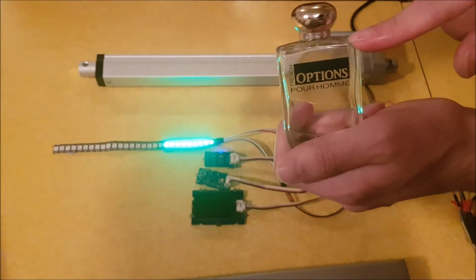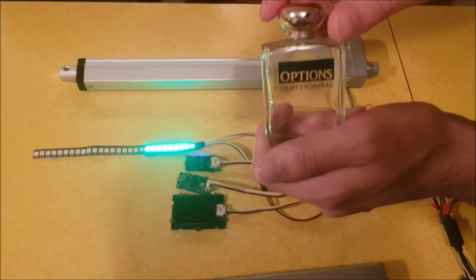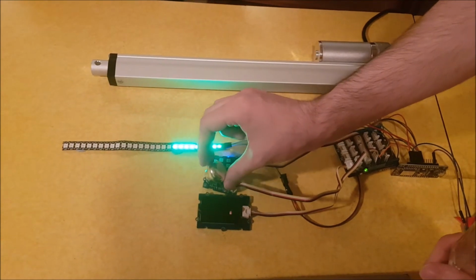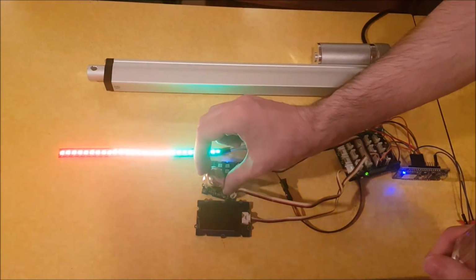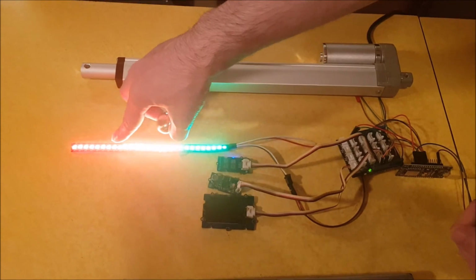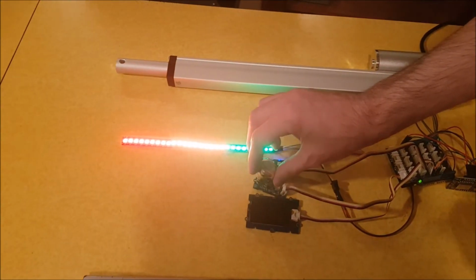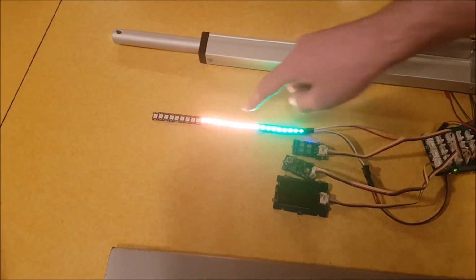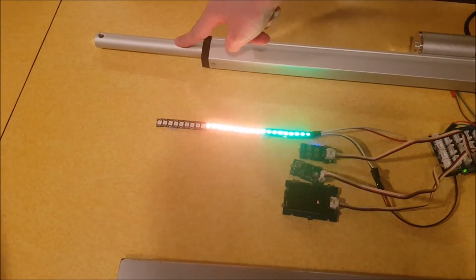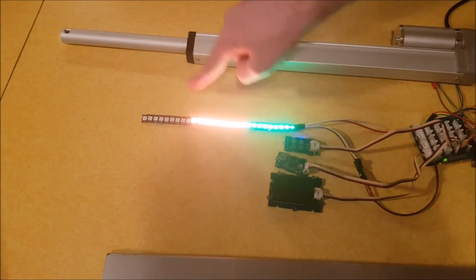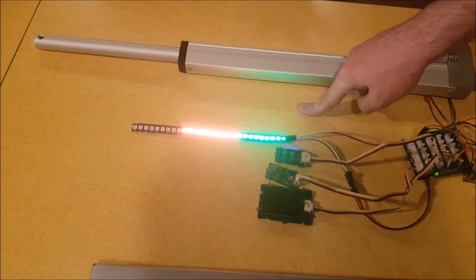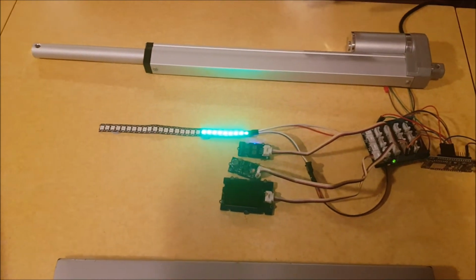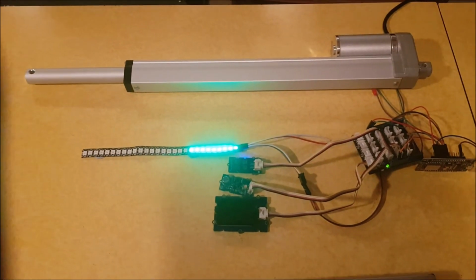Here we have some perfume which contains high concentrations of alcohol. When the bottle is shaken and some is put in the cap and we put it on top of the sensor to simulate bad air quality, the sensor automatically jumps to red, simulating high pollution. The linear actuator opens, and when we remove the cap, it goes to yellow, and the linear actuator carries on opening because it's detecting low pollution. However, when it detects green air quality, the linear actuator will begin to close because the air quality is green and the window is no longer needed to be opened.